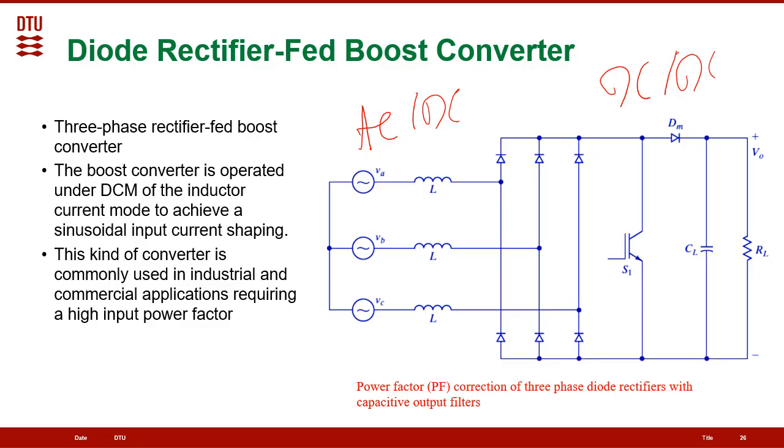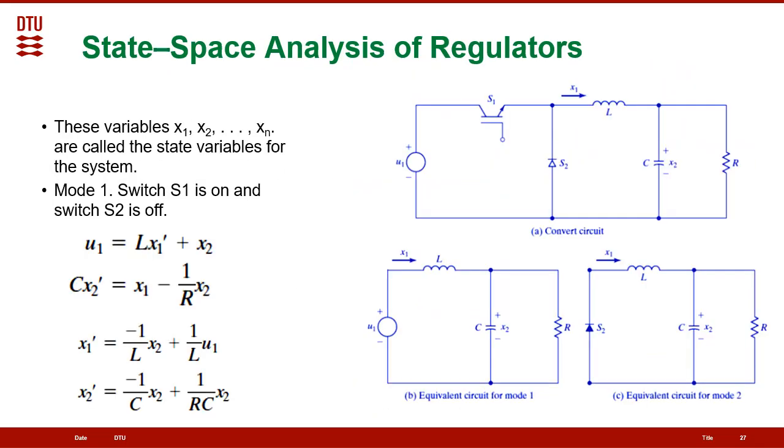Okay, before the last part, when we want to regulate DC converters, we need to design the controller. To design a controller, we need to find the transfer function. What does it mean? I have this converter, but actually what I'm looking for as a control designer is the expression for your converter. So we need a G of S.